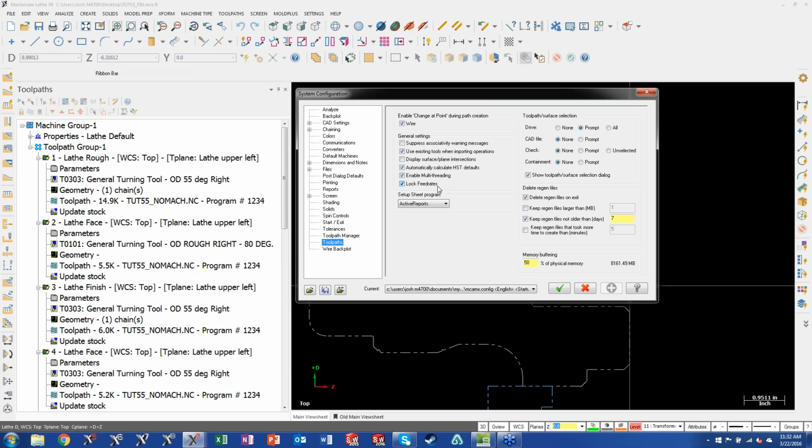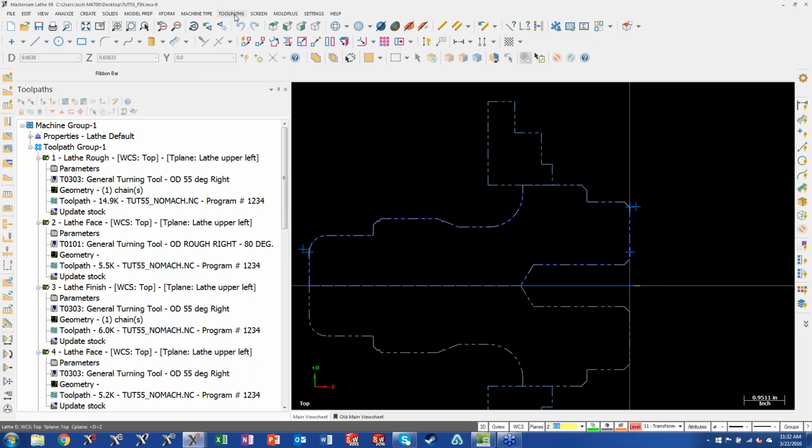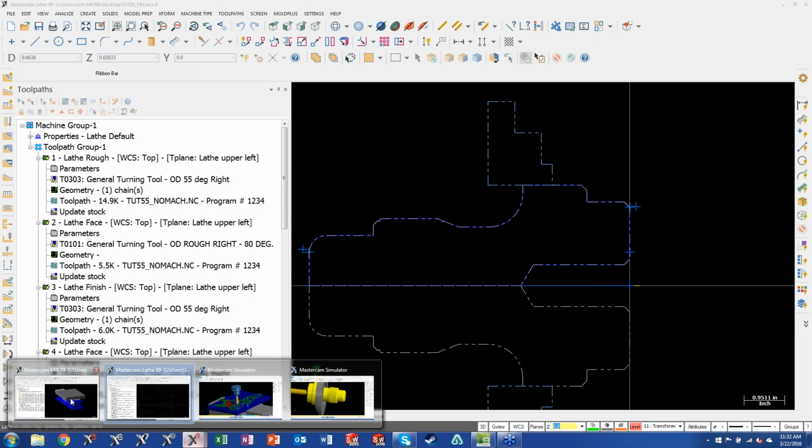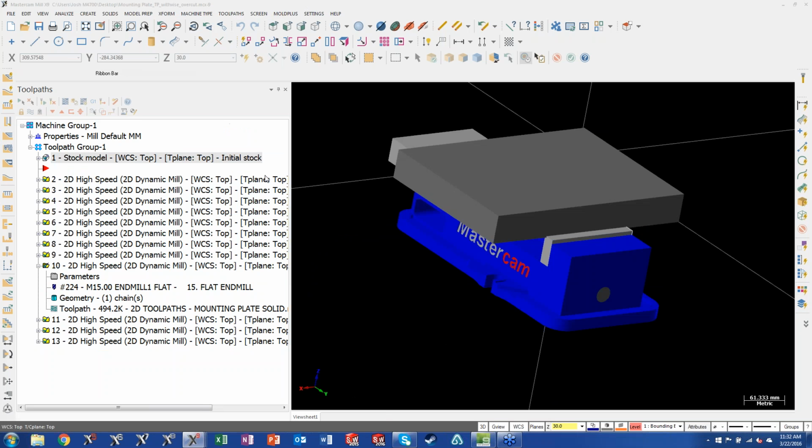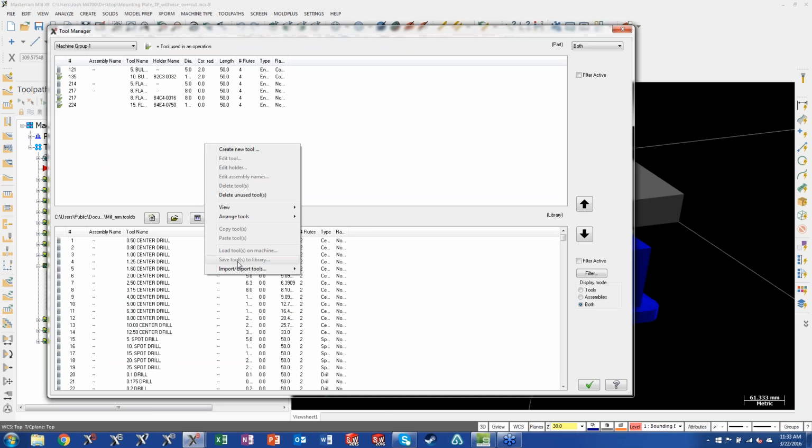Yeah, so what I find works best is if you can export the tool library as an Excel file. Just in Tool Manager, throw up a couple tools, right-click, export tools. Okay, so you do that on your screen. So the tool library here, let me pull up the middle one real quick. In Tool Manager, have a couple tools in here, import, export tools, and then convert a library to text, and then you also have from text. You want to match the text right here.